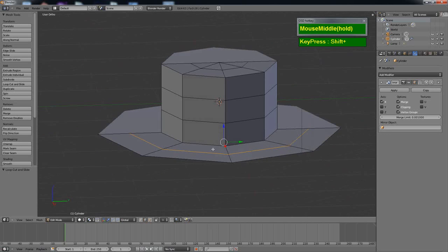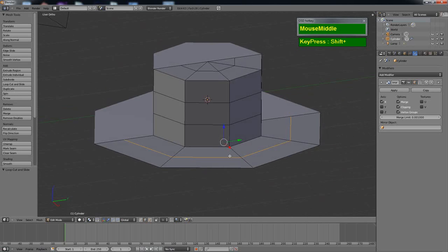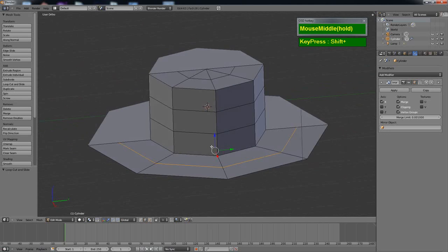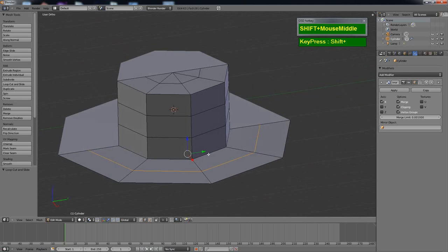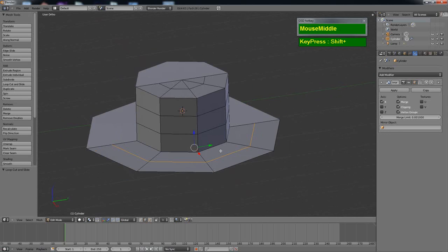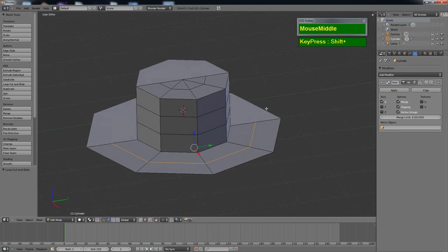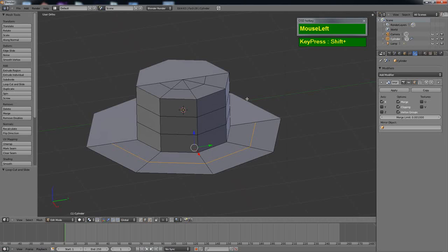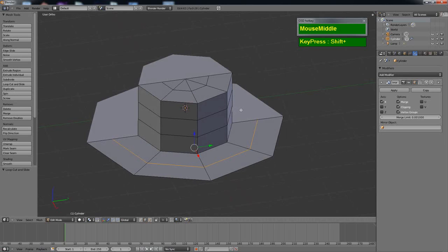Okay, but the hat we want to do today is a fedora, so we need to work with this shape to make it look like a fedora. So the next thing I want you to do is to apply a modifier called a subdivision modifier. Now you can add it here by clicking on Add Modifier and Subdivision Surface, or I prefer the shortcut, by pressing this combination, Control and then plus your top number row key.